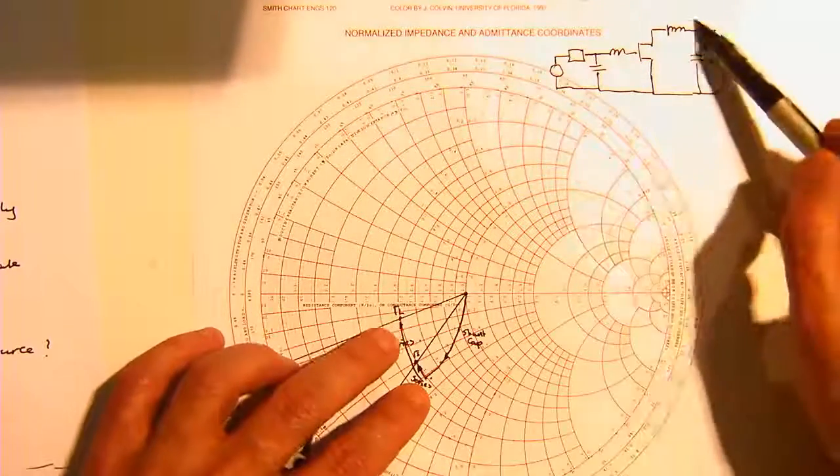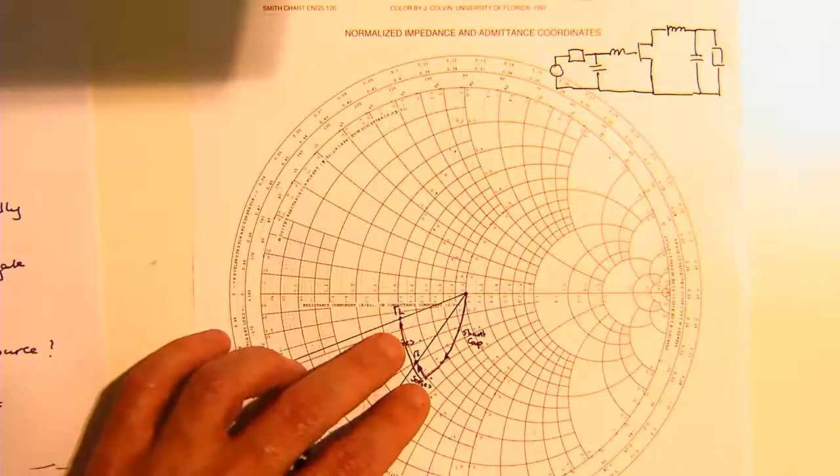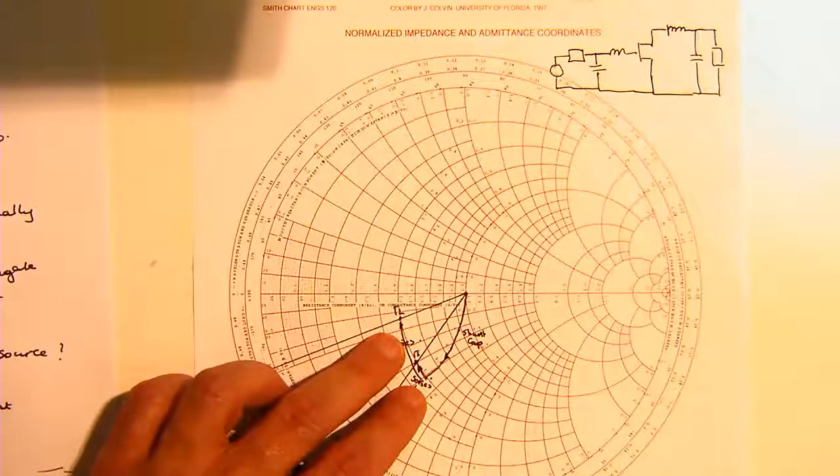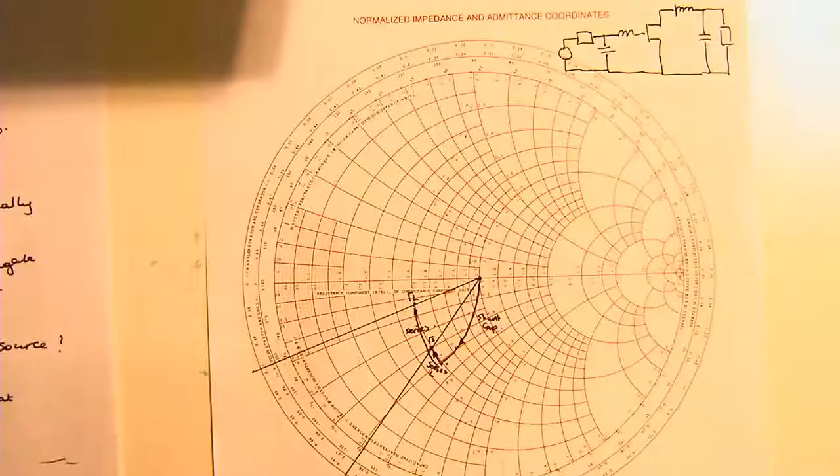Gamma L, we've worked it out, because based on this value you can do the same thing in order to work that out. Okay? So this particular device will give you the minimum noise figure. So the absolute minimum, you can't do any better than this if you follow this approach.